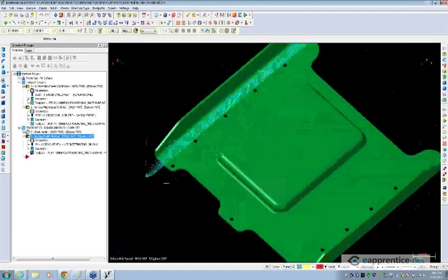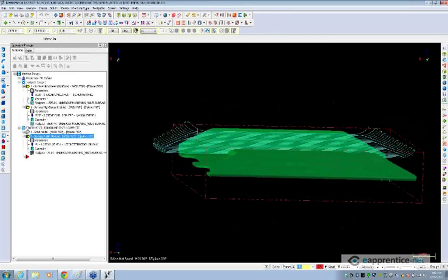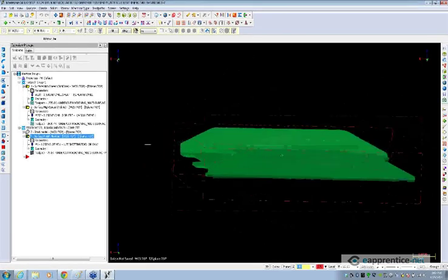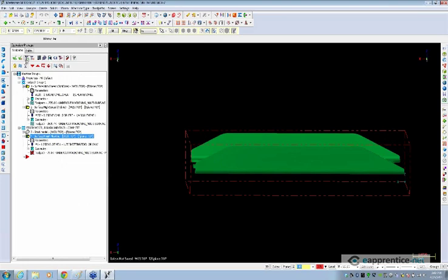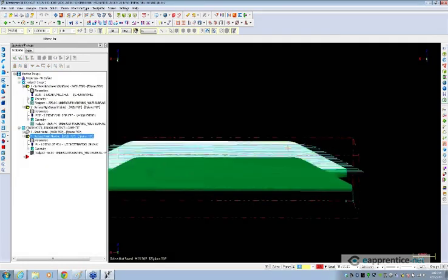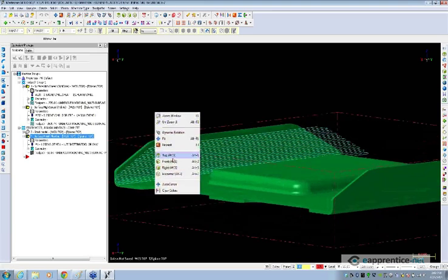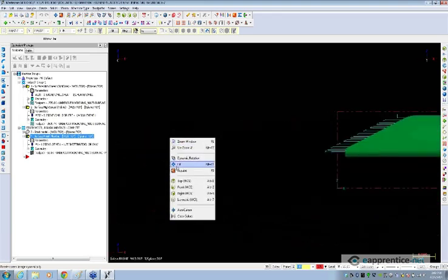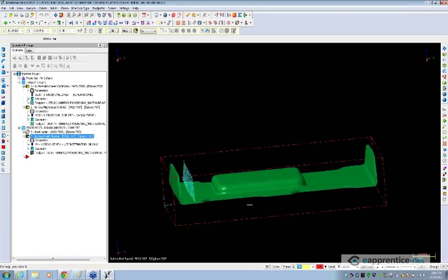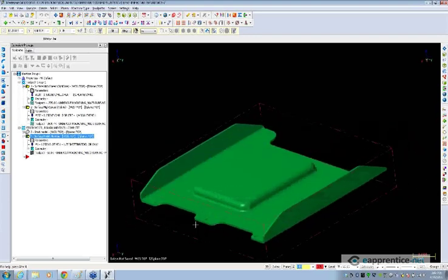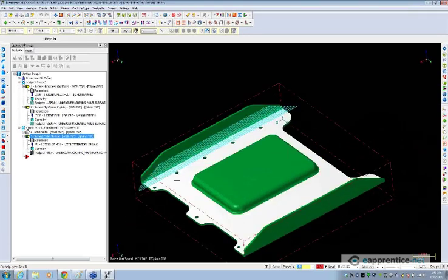Now in this case it's trying to do the retract motion up this way. We wouldn't want the arc in there, so let's disable those arcs. We're going to set the tangent arc angle to 0, and the tangent arc radius to 0. We're just going to use tangent line. And now we get some motion that's extended off of the edge. Let's look at this from the front view. Fit it to the screen here. We get some motion that's extended tangent off the edge of that undercut surface. So as long as we use enough tangent entry, that could technically work for us.